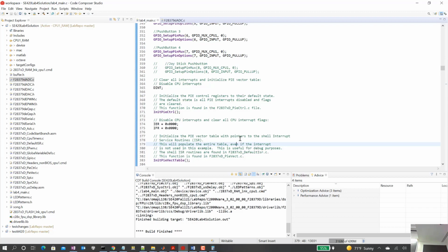The only reason I'm talking about this is it's one sensor that whenever the processor wants to know what count the quadrature encoder is at, it can read it immediately. There's just one register that's keeping track of this count, and this count is proportional to radians that the wheel is spun. All right? So counts relate to angle. And whenever you want to, the processor can just go boop, read that register, and now you know the angle of the wheel. Again, that's a very nice sensor. Kind of everything's happening in the background.